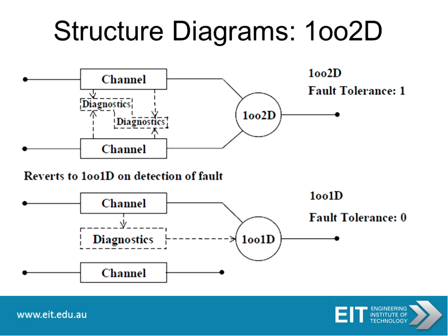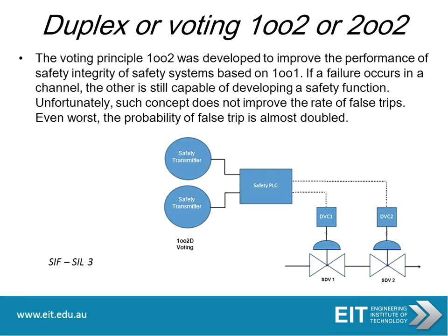So there's 1oo2 diagnostics. Again, you've got the two channels, but now we've got the diagnostics that were shown to you in the previous slides. And 1oo2D also added diagnostics, so that's improving the safety of the system by adding the diagnostics.